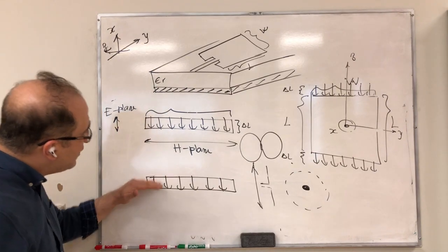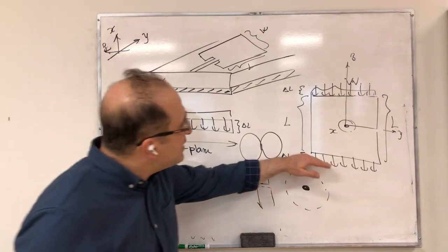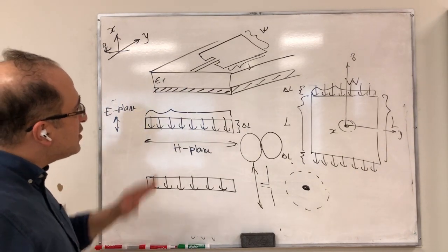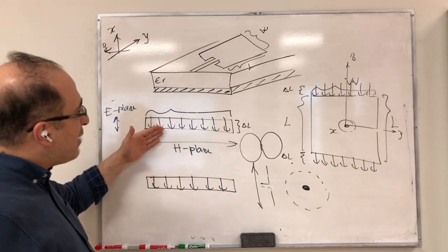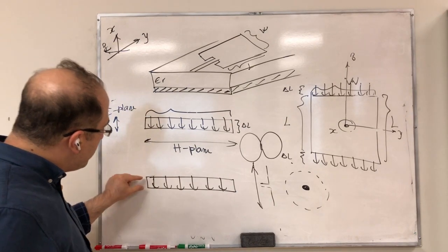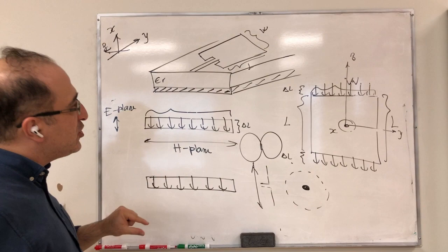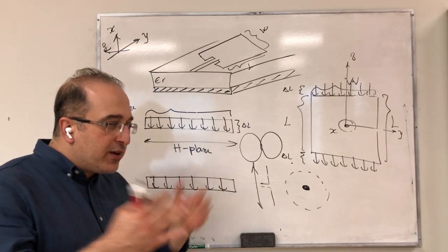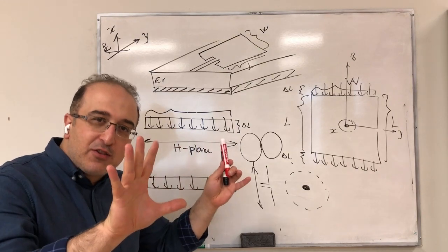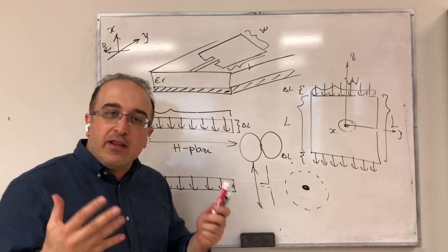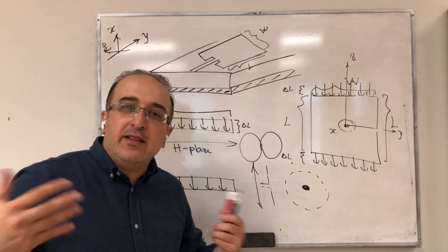The other thing that you can immediately see from the discussion of the microstrip antenna here is that, first of all, this is like an aperture antenna, with two apertures of electric field. With an aperture antenna, you have an aperture, and on this aperture you have an electric field distribution, and that's going to radiate for you depending on the way that you design this electric field.